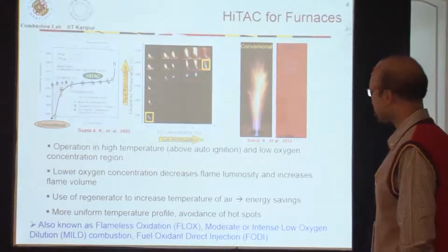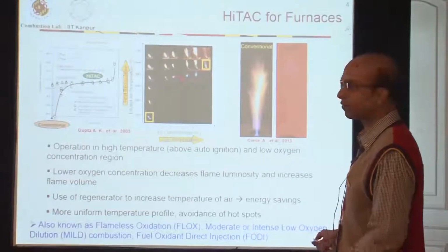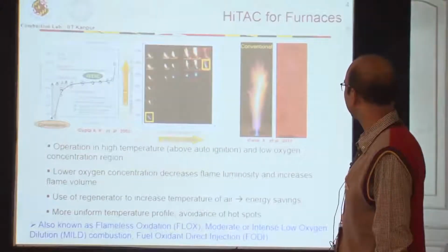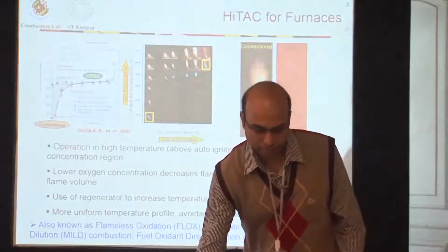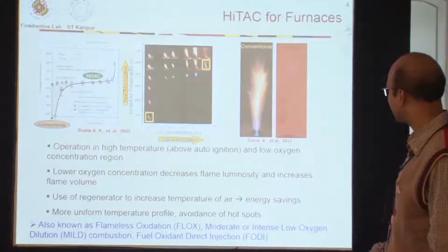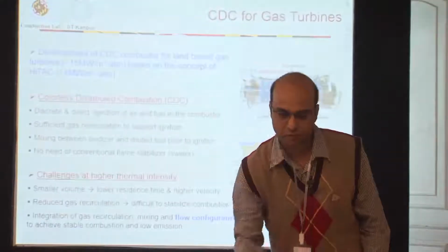And here are some of the photographs. This was some fundamental flame studies done at Dr. Gupta's lab. Your flames are mostly at lower oxygen concentration and higher temperatures, also known as flameless oxidation, mild combustion. Many other names have been suggested for this sort of flames.